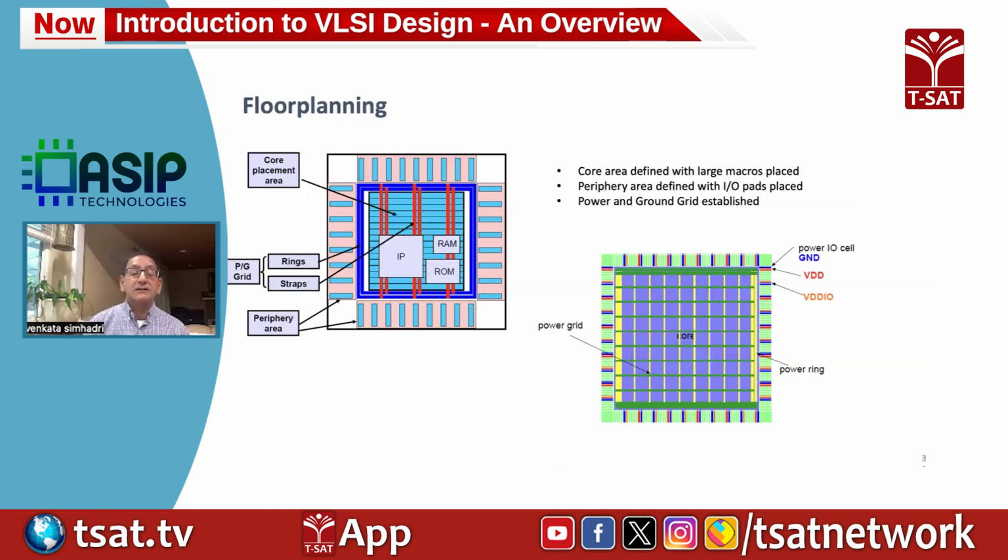So let's say the power source is coming from the periphery of the chip, and if your component is in the middle of the chip, you have to make sure that the power drop from the periphery to the center will not affect the performance of the component. So you have to make sure it meets the IR drop requirement as well. So you build a power mesh, and there are tools you can use to analyze that power mesh to make sure that the IR drop is within the limits.